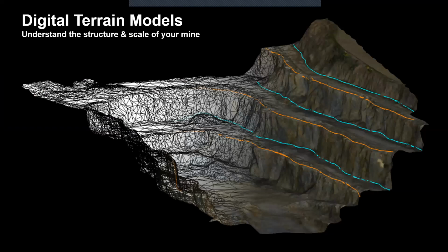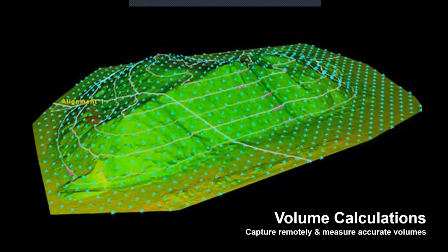In areas where we want to construct new structures or clear the land, and we want to do cut and fill activities, we can have digital terrain models. For doing the analysis, we can do volume calculations for your quarry. So we can calculate how much material will be required for land cut and fill situations, and how much construction material will be required for a particular site, so that we can make the right estimations and have better budgets for the buildings.